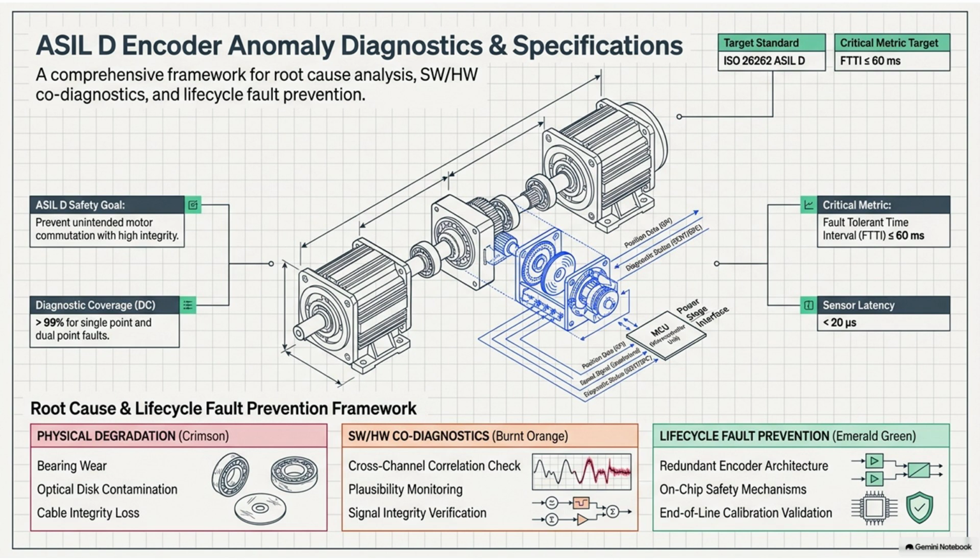Okay, so an optical encoder uses light to measure the rotation of the motor. You have this precision glass disc with microscopic slits and a light-emitting diode, an LED, shining through it to a photodetector. Which sounds great in the lab. Right, but if you are putting a delicate glass disc inside an electric motor housing, you're immediately dealing with the coefficient of thermal expansion. Exactly. The housing is metal, the disc is glass. Yeah, and they expand and contract at completely different rates when exposed to the extreme thermal shocks of a car.